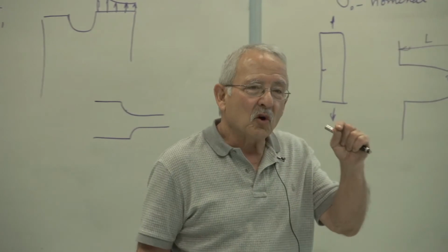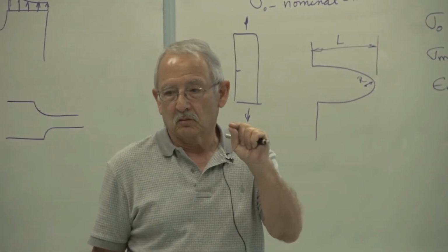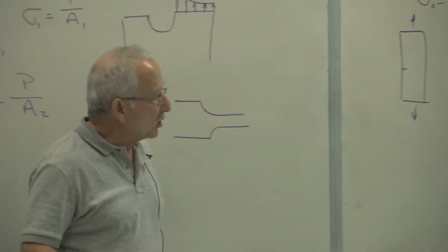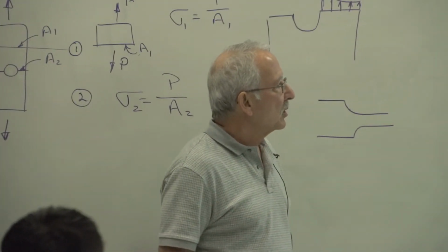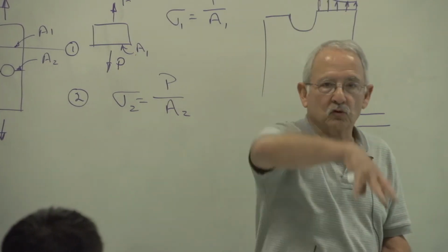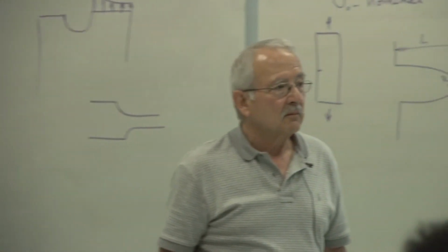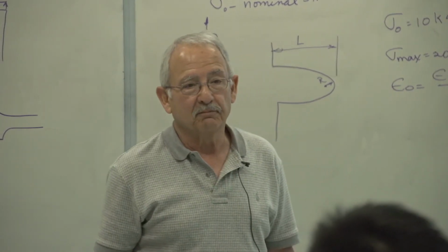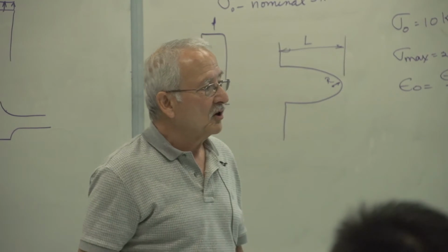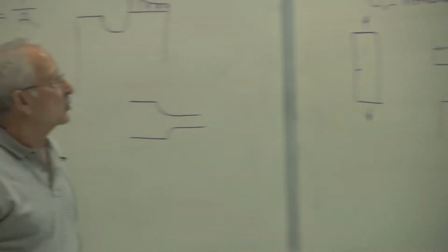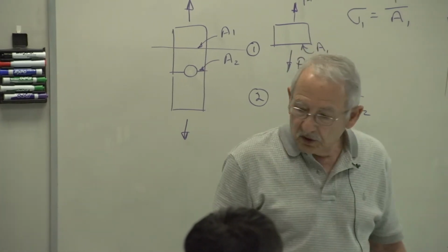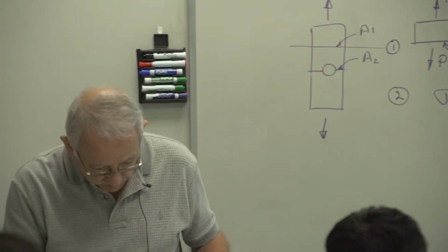The increase of the load is very, very gradual, so there's no speed associated with it. There is such a thing called dynamic loading. If you have a beam and you drop a brick onto it, the effect of that is much more than just putting the brick on top of the beam. That's because of the dynamic effect of the load or the kinetic energy that is associated with it. So this is a little bit about stress concentration.